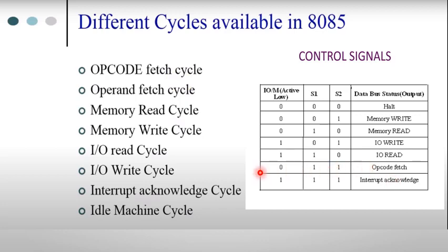So the interrupt acknowledge cycle is an input related thing. While the microprocessor is performing any IO related operation, the IO/M bar pin will be active high. When it is performing a memory related operation, the IO/M bar pin will be low, or 0.